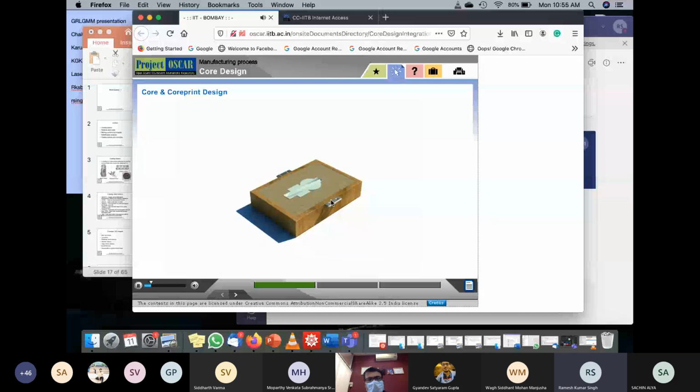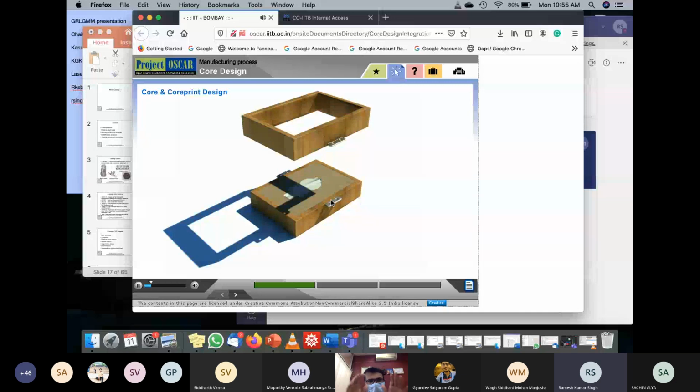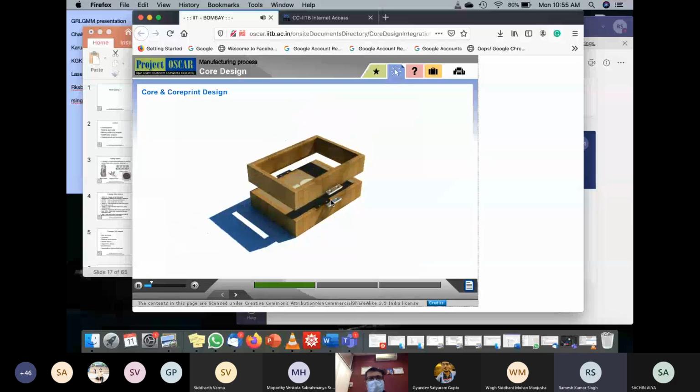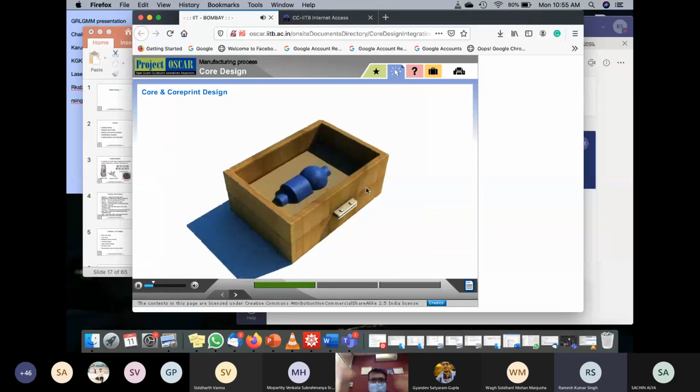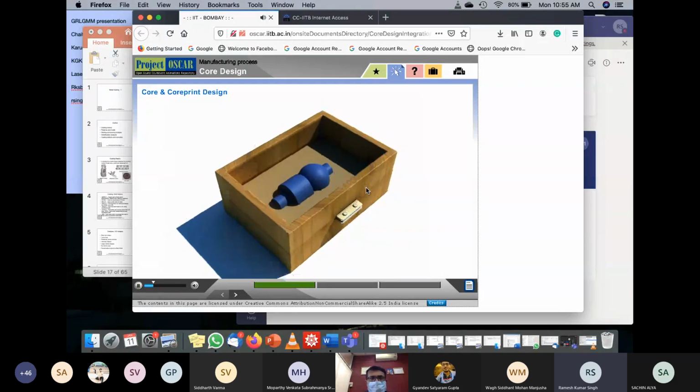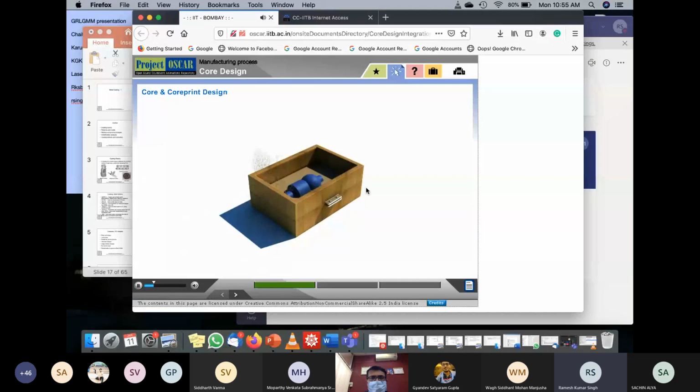And then you put the other box on top of it. The bottom one is drag, the top one is cope. And then you put the other half pattern on top of it, and then put the sand, ram it. So now you have the pattern inside these copes and drags totally rammed. The sand is packed.